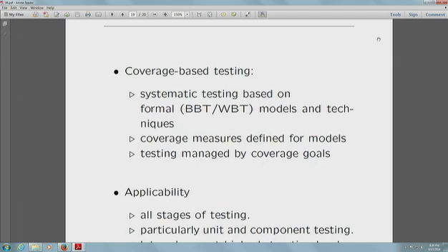It can be black box, can be white box. When you do coverage, you want to cover all the major functions, for example external functions, or you can cover all the internal components. If you are covering internal components, you are doing white box coverage. If you're covering external functions or your external finite state machine modeled behavior, you are doing black box coverage, right? So when you do coverage, you can do black box or white box.